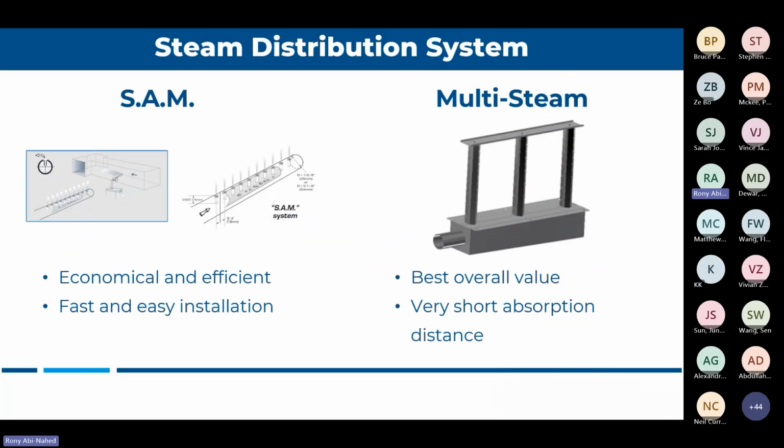So now we spoke about generators, where you're boiling the water. And then you need to push this water somewhere. So that's where we get the grids. You have two options when you're designing grids. You can go with a single tube, mainly for small to mid-size applications, where you just put one wand in the duct and you shoot humidification directly in the duct.